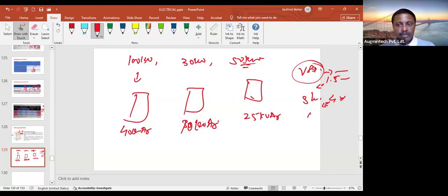For lathe machines and the like, I could use an auto transformer starter, which would be 3 times the normal or full load current. So if this is 40 kVAR, we may not guarantee that only 40 kVAR is going to flow. Maybe 30 kVAR would be the reactive power at the time of starting, or maybe 20, or maybe above 45 also. So that's the reason we have to split all these capacitors in a common capacitor panel.